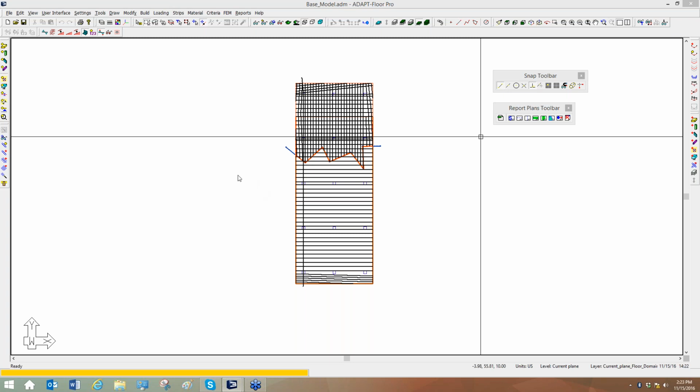And then the next question is, do support lines in a specific direction all need to be parallel? The answer to that is no, they don't. Support lines really just allow the user to generate data points. In reality, it's a data line. It's a design section for zones in your slab. So I'll give you an example.